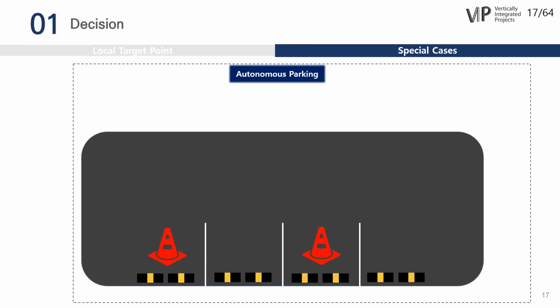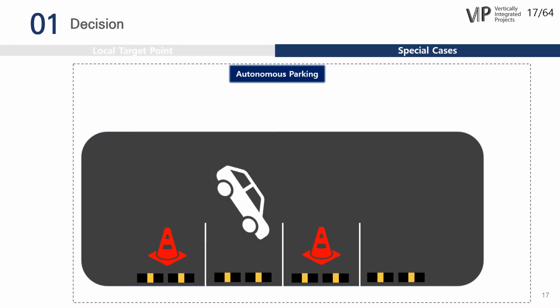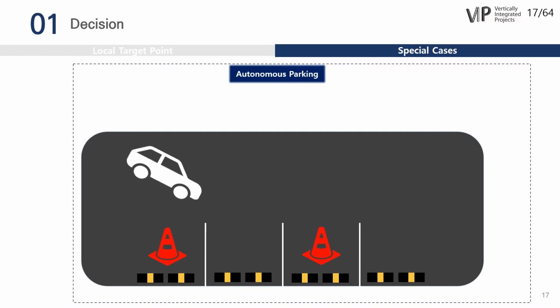We will look at parking with the image data. After recognizing the parking sign, the vehicle changes to parking mode. By reducing the speed of the vehicle, we can reduce bouncing of the LiDAR, and try to park according to the number of parking spaces received from the LiDAR. After a successful orthogonal parking, stop for 3 seconds. Then change to reverse gear and go back to original position. After that, driving along the GPP route.